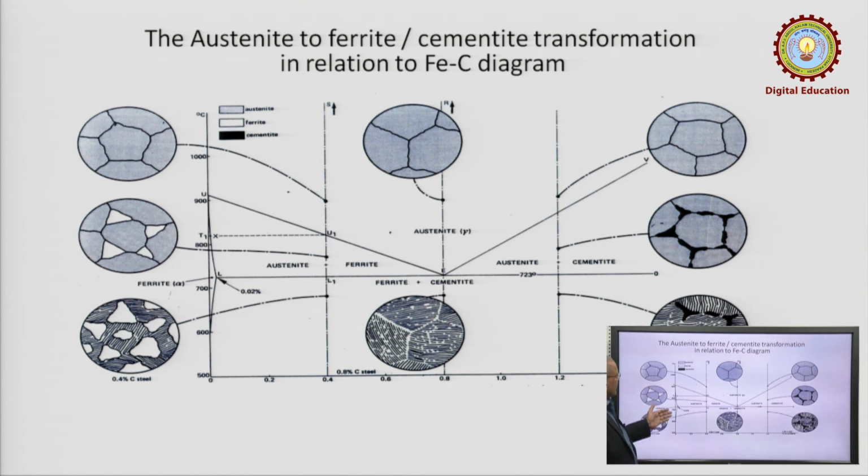Again, you can make a comparison here. You can see this is 100% austenite, 100% austenite, 100% austenite. But as you continue into the different carbon percentage regions, this is 0.4%, 0.8% and 1.2%. So, if you draw a vertical line at the different points, you want to know what the microstructure of the material is. You can see here this region falls where 100% austenite is there, this region indicates a mixture, and this region again indicates a different mixture. Similarly here and similarly in this case.